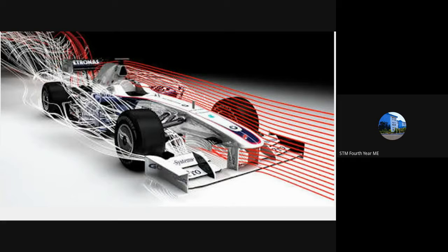But during cornering and so on, it tends to lift up, because at some point the air escapes underneath the car due to cornering. In the cornering condition, you know that there is a weight shift occurring from one position to another, and due to that weight shift, one of the wheels, depending upon the turn, lifts up a little. Due to that lifting, there will be a small gap at the front end of the vehicle.